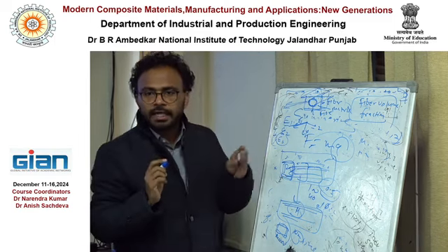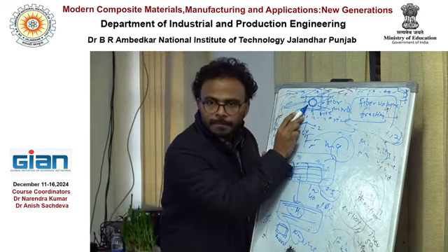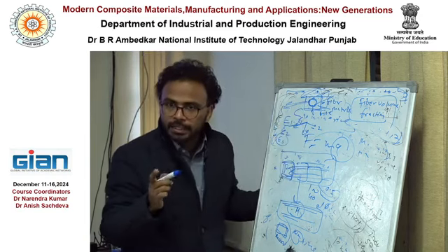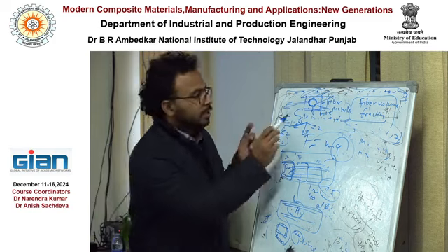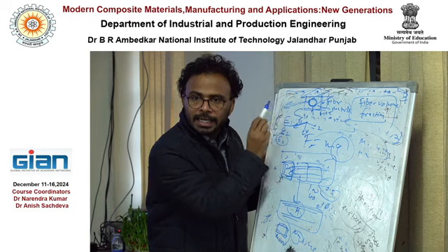You can read the article. I have done this, or others have also done this. There is an article. Just create the RBE first. You are calculating mechanical properties, right? You are evaluating mechanical properties. Just create the RBE. Apply the load or deformation like that.